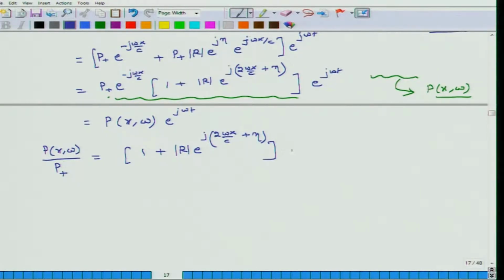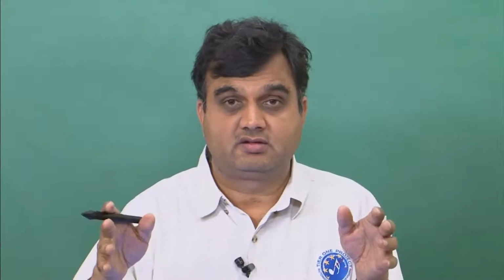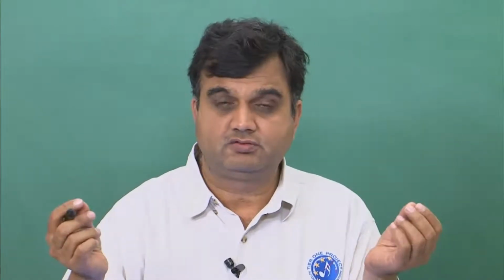Okay. So this equation is coming directly from here. Now, this is my fundamental equation. And what is our goal? Our goal is to figure out the value of R in terms of the readings made by the microphone, because we can use the microphone and find the values of pressure at all locations in the tube.